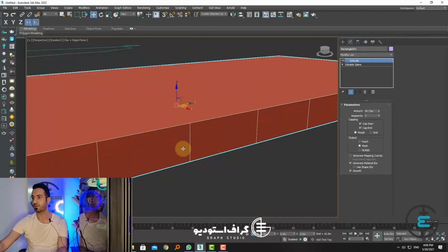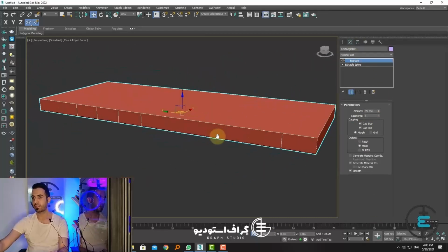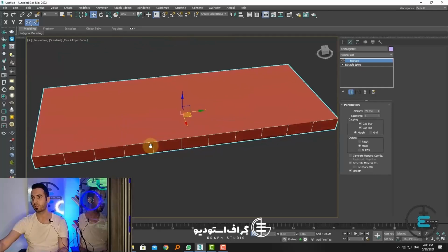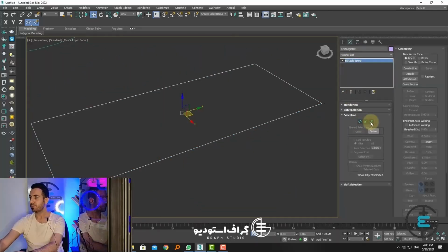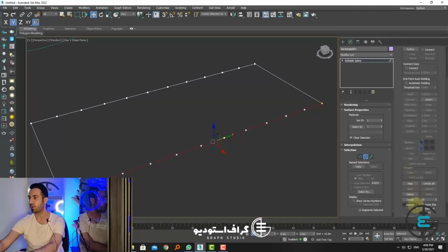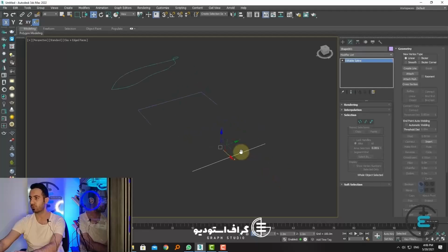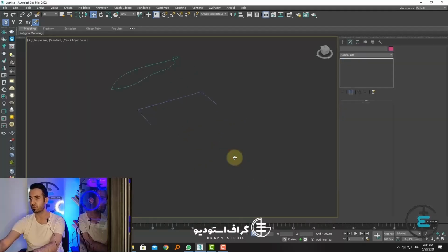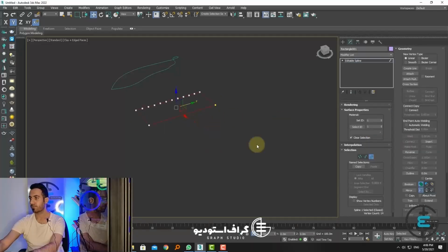Now the shell comes up. It doesn't take that inside thickness anymore. Open Spline, check here that Closed is written. Did you see that Open is written? Understand that there's something wrong, and you must definitely do the Outline operation. Well, here I selected the Spline, and here Outline. And when you activate it, you see that there's an offset value. You can give it a side line of a certain size, whether outwards or inwards. We always do this in these architectural plans.